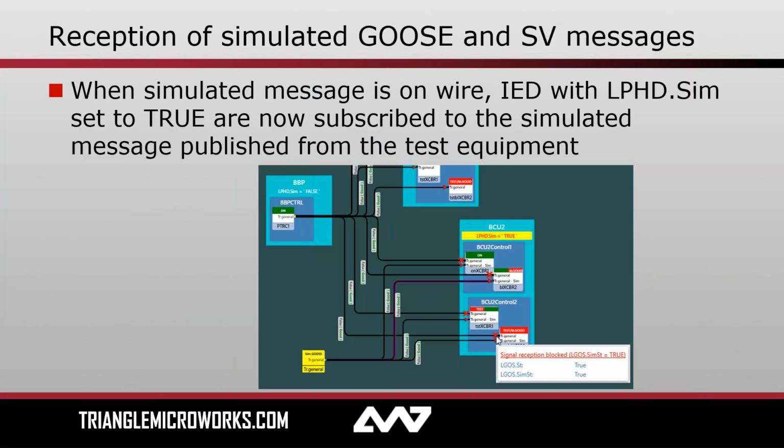Yes, correct, because that's exactly the purpose why we introduced Op OK, that we can observe if a test would be successful without really having the breaker tripping. Let's assume you want to do a protection trip from a relay, so you want to know the performance, but you don't really want to trip, but you still want to know if it would have tripped. That's exactly what we can use. So you don't need to physically remove the wire, how we would do in a traditional environment.